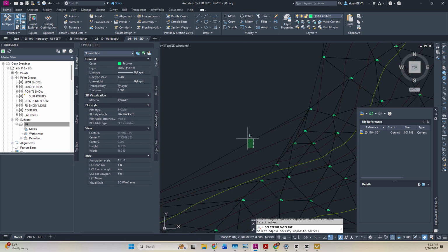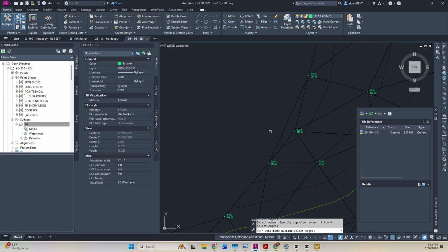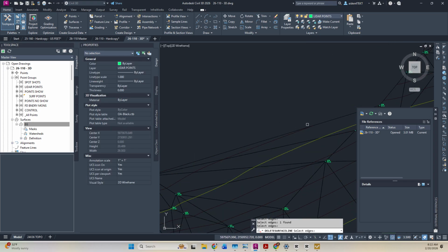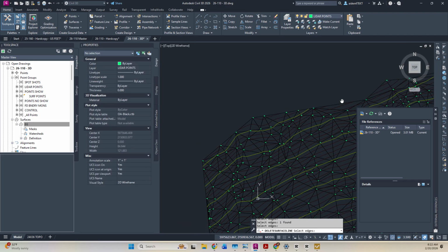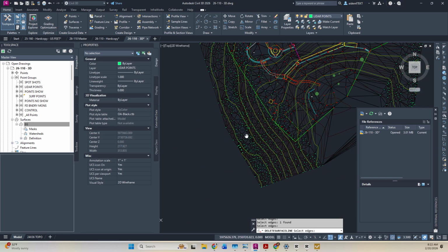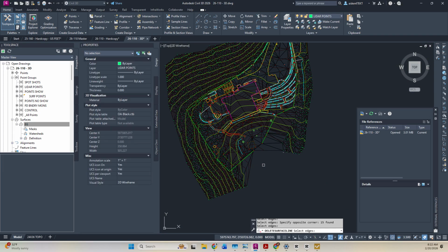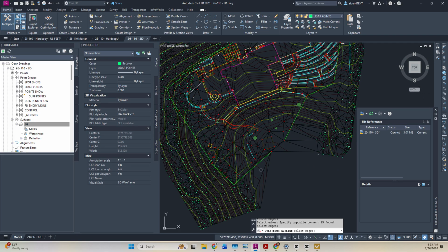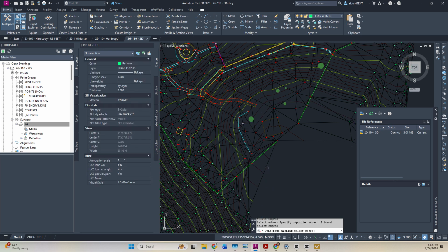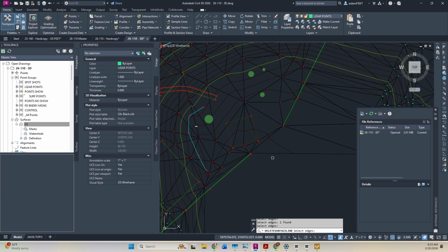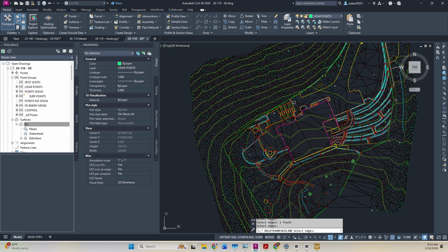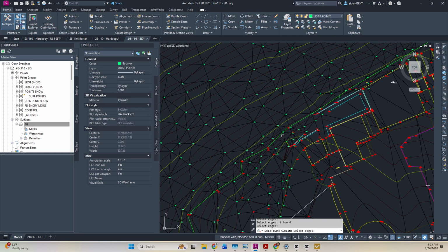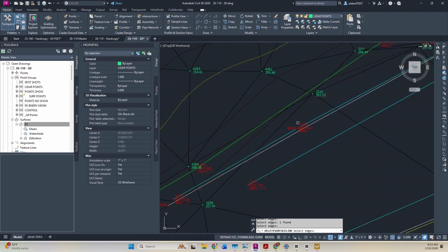Start trimming these lines here. You want to trim lines where you don't actually have a shot between them that's a reasonable distance. So it's good there. Same thing with these. We don't have a shot really between those. It looks really good already. Let's see here. So this is how we do some cleanup. This looks pretty good already. Not much here. There's a retaining wall.